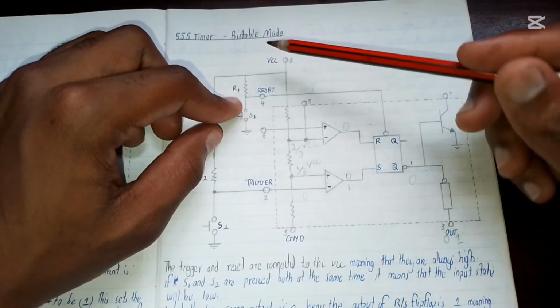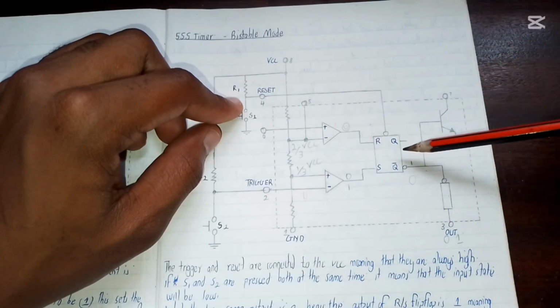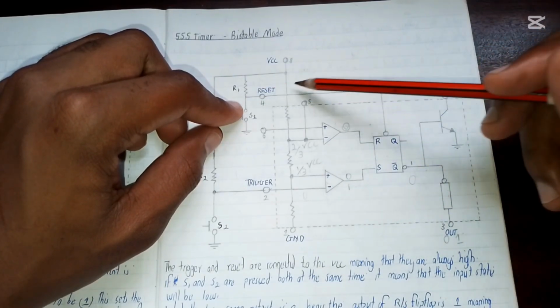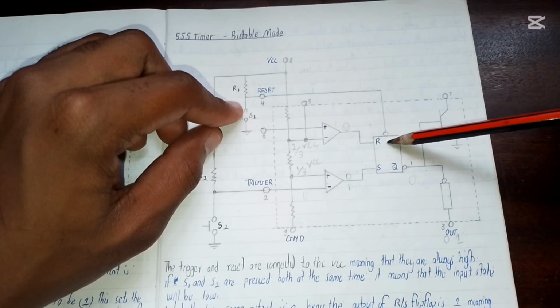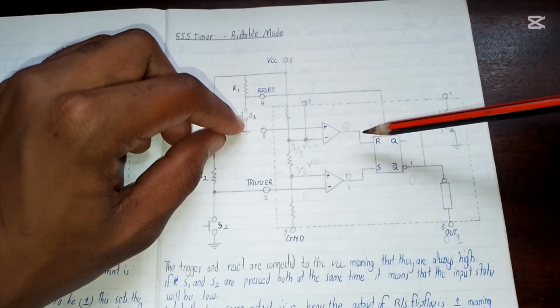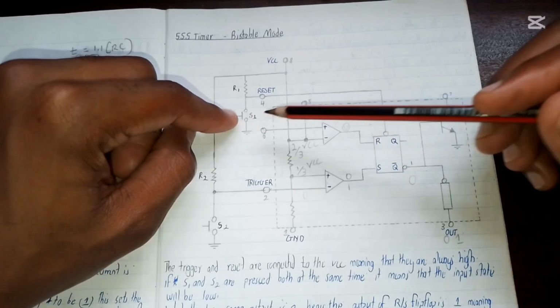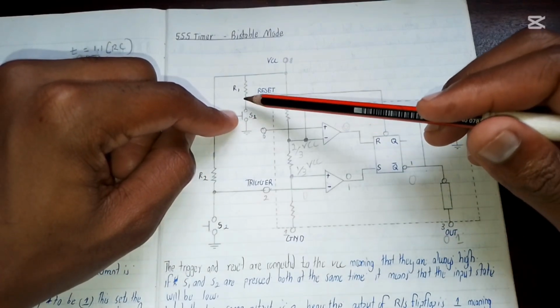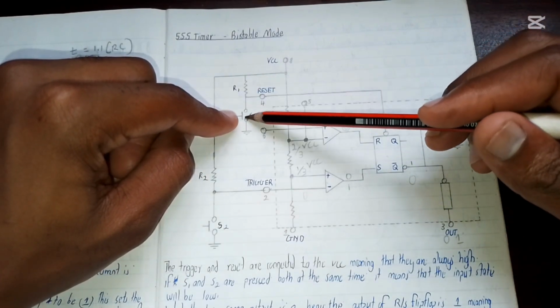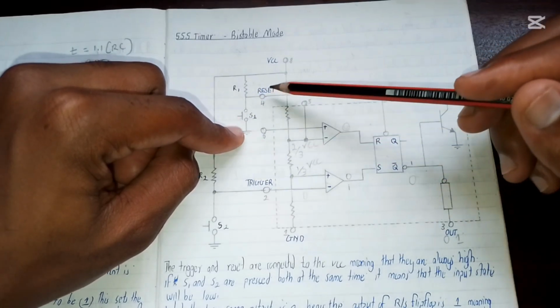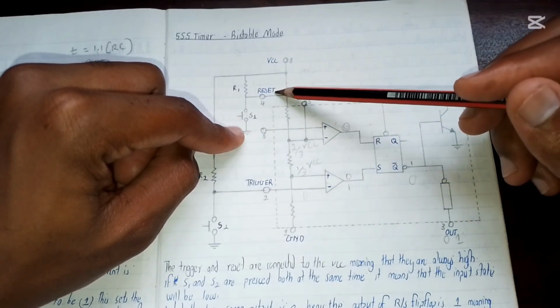If you can see, the reset pin is set high also. It's also set high, but it has an inverting point here. So meaning that because it's high, it's going to be turned to 0. So the only way to turn it on is by pressing this, then it's going to be on. Once you press this, then current will be choosing the shortest path, which is going to ground. Once it goes to ground, this will be getting a 0 input.